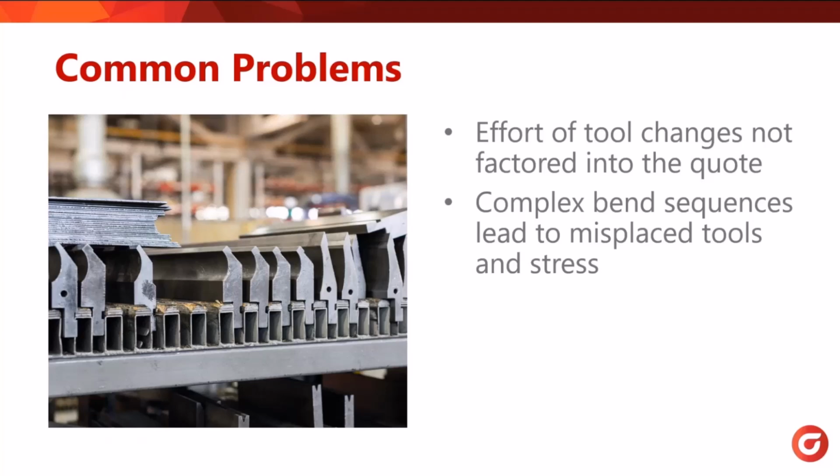And then the second is going to be some more complex bend sequencings or bend setups leading to misplaced tools or stress on the operator, right? So if we've got some more complex parts, we tend to see a lot more setup configurations between programs. We're having to continually add and remove tools to the brake, and that can lead to misplacing those tools. And then, of course, just general wear and tear on your operator through the physical labor of doing all of that tool changing.